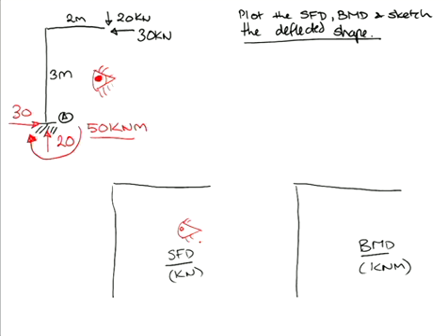Now while you're doing that, I also brought my model of my corner that I forgot to bring last week, just to show if I have a load down, I said you'll either have an inner corner where you get tension on the outside, or if I apply my load up, an outer corner where you get tension on the inside, of both. So you'll only get your corner doing that or that. The only time you would get tension on one side and tension on the outside is if we apply a moment at that corner, and I won't do that to you.